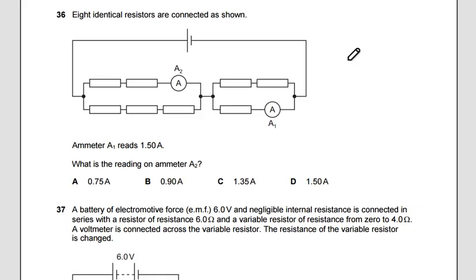So for this parallel connection, we have the same potential on both branches. Okay, and as potential is equal to IR, we have I1 R equal to I1 prime, let us say, times the resistance, which is 2R.